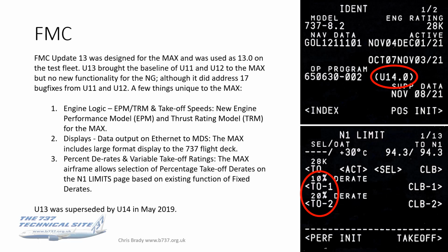So you can really bring the engine power back, which, as I say, if you're a bean counter, that saves you money. If you're a pilot, that means that you're operating further away from the red line, so you've got less chance of having that engine failure at V1, because the engine is having to work less hard. Anyway, update 13 was superseded by 14 in May 2019. So you should all have update 14 by now.